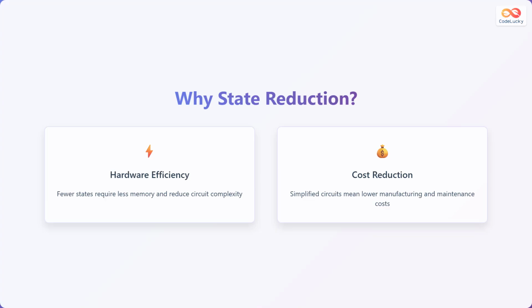Why is state reduction important? There are two main benefits. First, hardware efficiency. Fewer states require less memory and reduce circuit complexity, leading to more efficient hardware implementations. Second, cost reduction. Simplified circuits mean lower manufacturing and maintenance costs. Reducing the number of states helps in creating simpler and more economical systems.